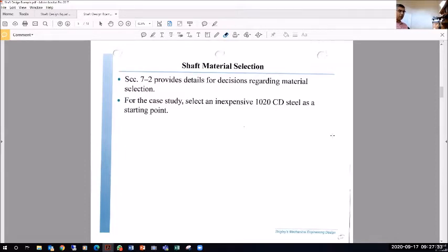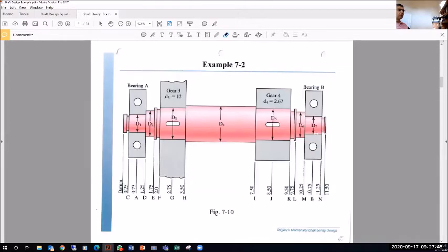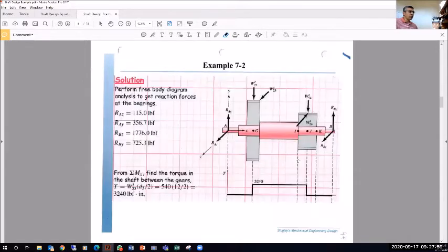And remember, the main function of a shaft is to transmit power through a torque. So as it is transmitting the power, it is subjected to these high forces, and we definitely do not want it to yield. So after looking at a material, the next step would be to do our stress analysis calculations. The first step is to find the internal forces, knowing the external forces.